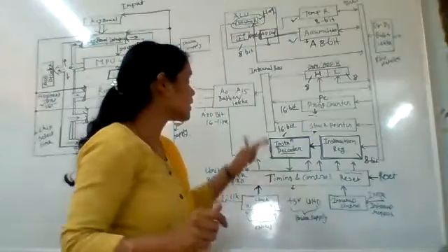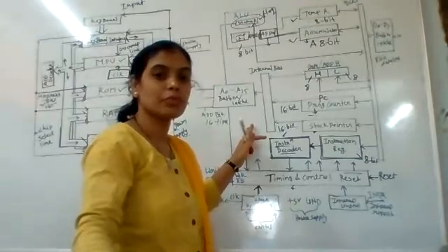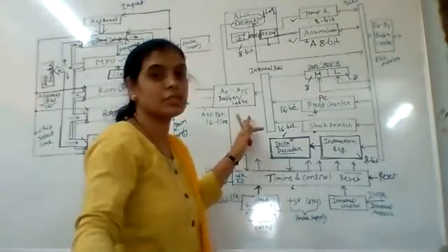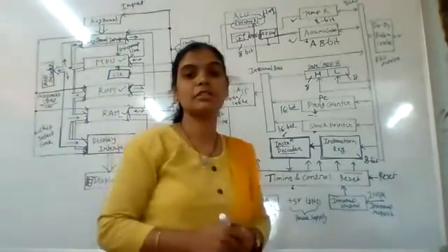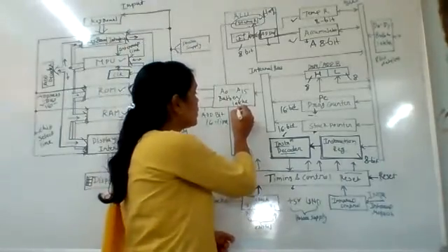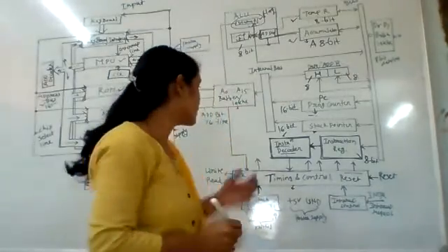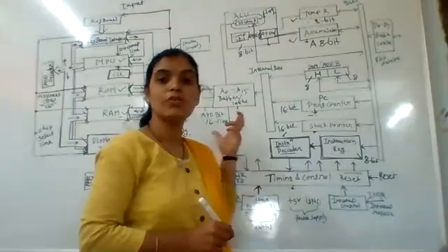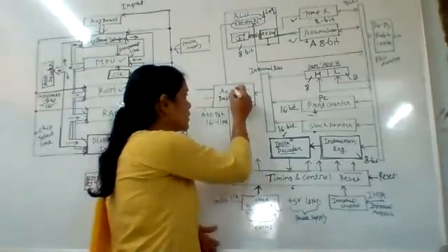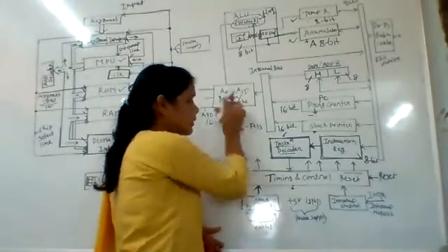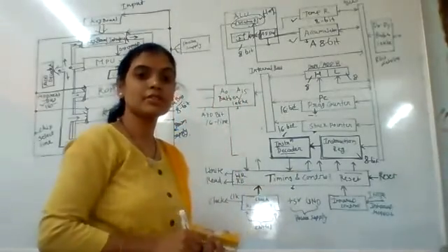These are the different blocks and registers in a generic microprocessor. Here we again see the buses: the address bus and the data bus. In this generic microprocessor, a 16-bit unidirectional address bus carries the address of memory and peripheral devices. It is identified as A0 to A15.